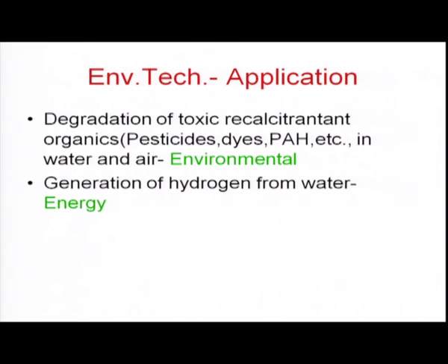And using titanium dioxide, we can destroy all these toxic organic compounds, pesticides, dyes, polyaromatics, everything, especially with nano dimension titanium dioxide or the doped one. We can completely degrade them into carbon dioxide and water, and any chlorine present is also eliminated. So this way, titanium dioxide is going to be the future technology of the advanced oxidation process, in which we can combine solar energy so that the cost will be considerably reduced.